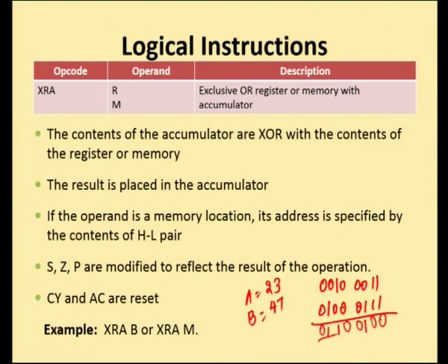So, finally, read it as a hexadecimal, which is 6 4. After that, the 64 is stored in the accumulator. After executing this instruction, the accumulator content will be changed. Before the execution we load our required data, and after executing, the resultant value will be stored in the accumulator.